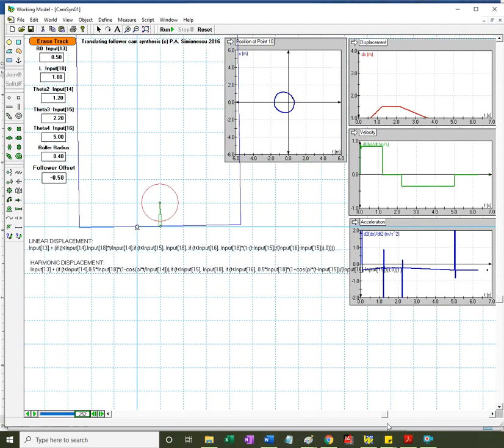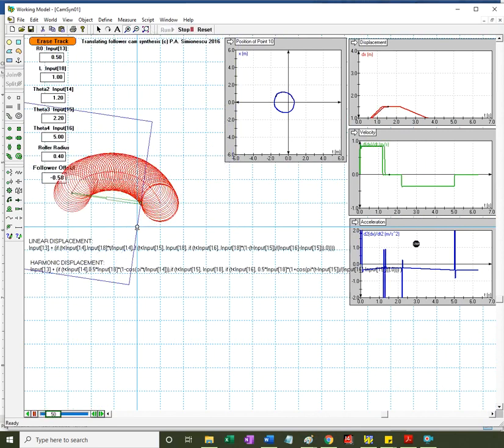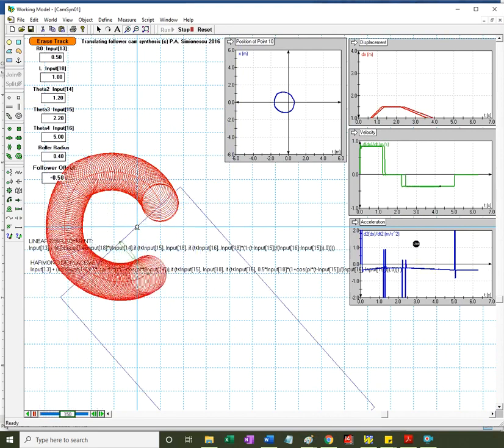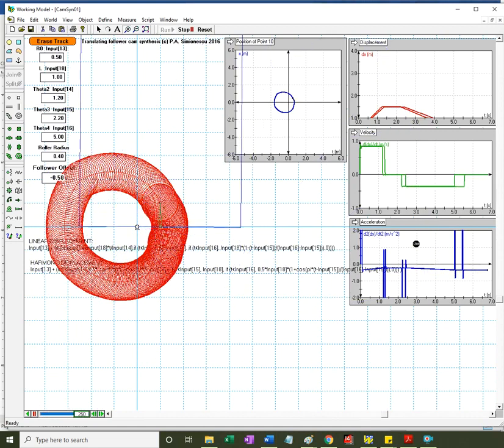So yes, same as with gears, you can have a situation where the cam comes back over a profile that was already generated. Say you in good faith generate this cam the way it's shown here as the follower envelope, but if you put it on the machine, you will see that it's not going to generate the desired motion because of the undercut.